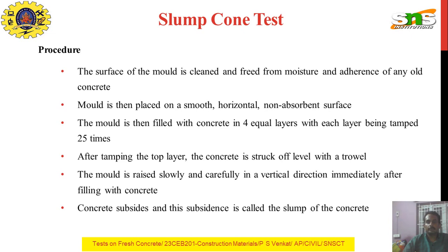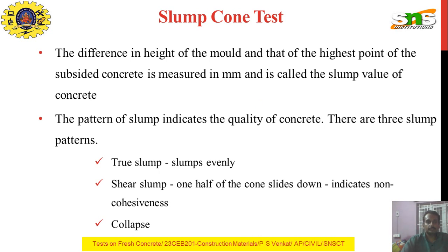After removing the slump cone mold, the concrete subsides and the height of subsidence is noted as slump value. The difference in height of the mold from the highest point of the subsided concrete is measured in millimeters and it is noted as the slump value of concrete.